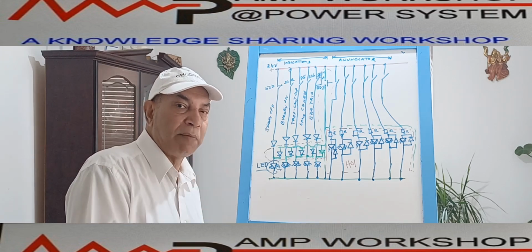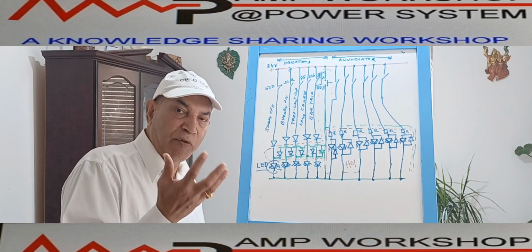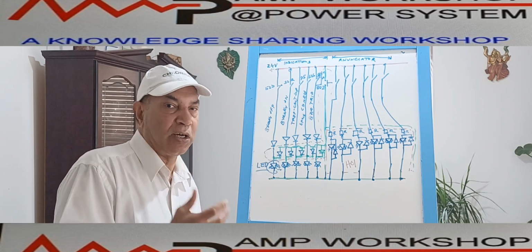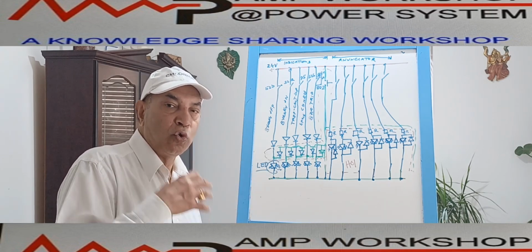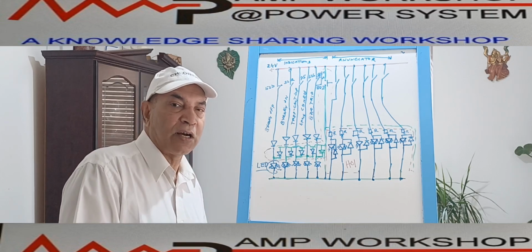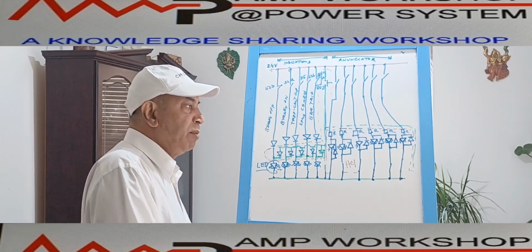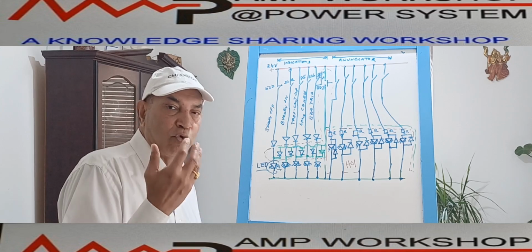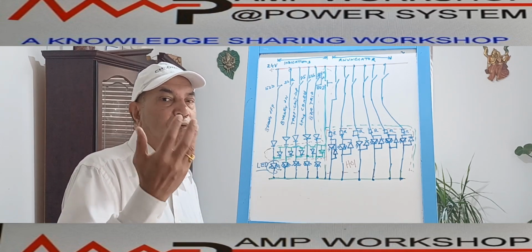The relay which we have used, the relay itself needs a power supply. That power supply is either 48 volt or 24 volt. Similarly, we use various transducers in the switchgear for the conversion of various parameters. Those transducers can also withstand only 24 volt DC or 48 volt DC, most of the transducers. Similarly, the alarm annunciators which are available in the market can withstand only a maximum of 12 volt, 24 volt or maximum 48 volt.